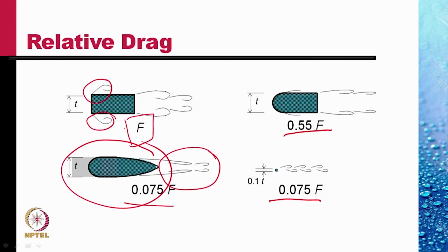In fact, the aerodynamic drag of the spokes of a bicycle wheel is quite substantial. Those spokes are cutting through air, have a circular cross section, and so add a lot of drag because there are a lot of spokes moving at the same time.